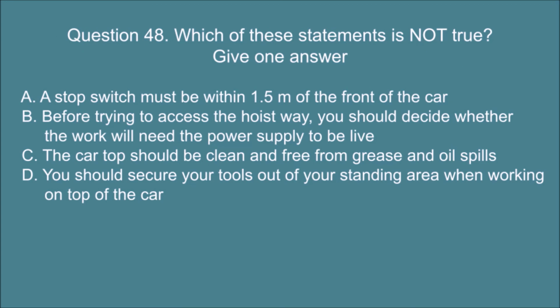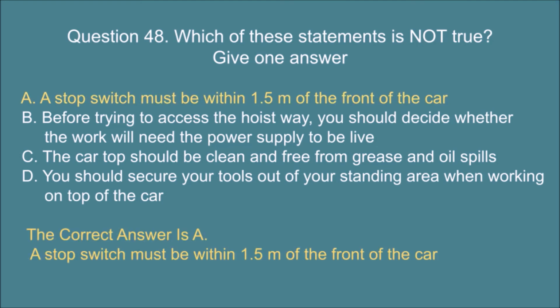Question 48. Which of these statements is not true? Give one answer. A. A stop switch must be within 1.5 meter of the front of the car. B. Before trying to access the hoistway, you should decide whether the work will need the power supply to be live. C. The car top should be clean and free from grease and oil spills. D. You should secure your tools out of your standing area when working on top of the car. The correct answer is A. A stop switch must be within 1.5 meter of the front of the car.